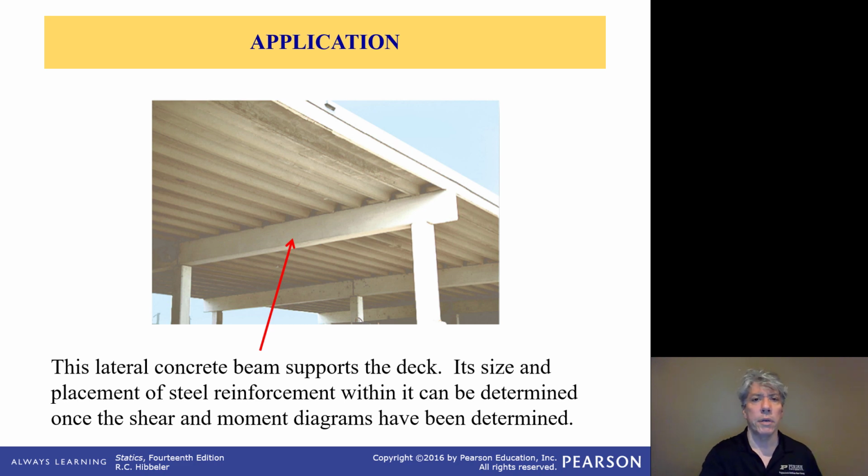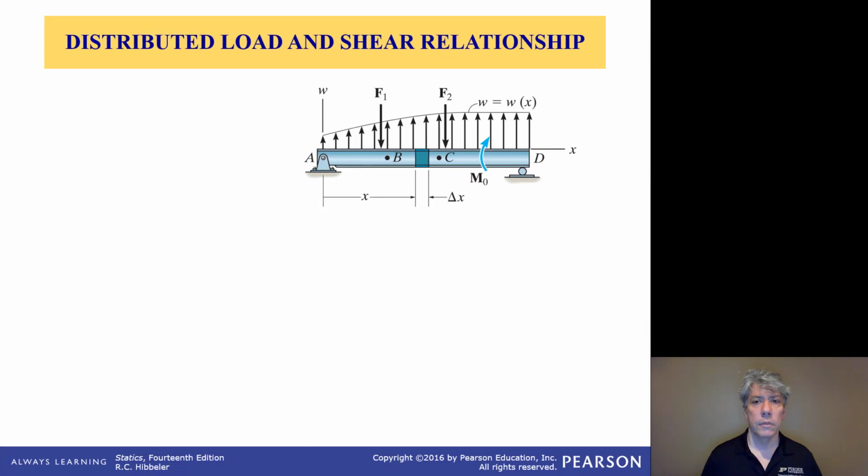Well, it's really important that you understand how the shear and the moment and the external loads relate to one another on a little bit deeper and more mathematical level than what we've considered so far. So we're going to take a beam that has a fairly complicated loading scenario. You notice there's a distributed load actually acting upward and with non-constant magnitude. So you notice on the left-hand side of this beam at A, the distributed load is up but relatively small.